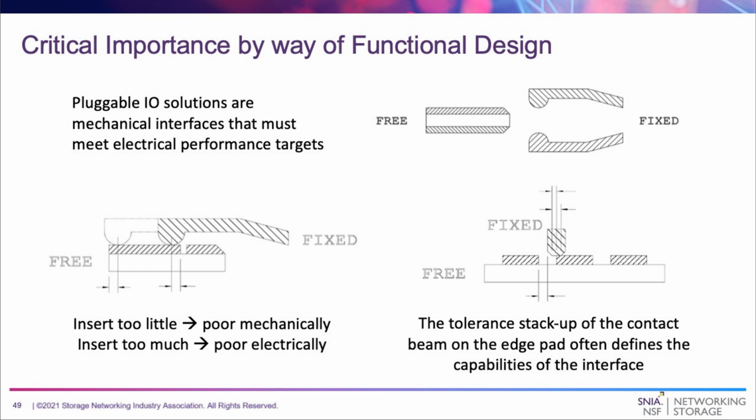So in terms of defining the mechanical interface, we typically use terms like fixed side and free side. The fixed side defines the connector that accepts its mate upon mating. This is commonly referred to as the receptacle or the socket. The free side defines the connector that penetrates its mate during mating. This would be like the plug or module, paddle card or edge card in common nomenclature.